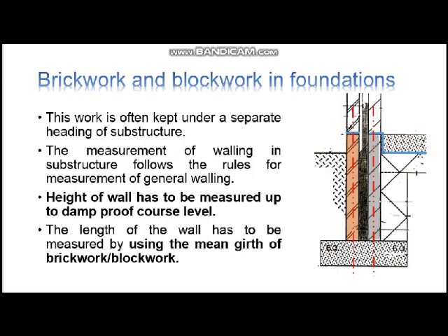Now we go to brickwork and blockwork in foundation. Normally it will be measured separately. So this red color indicates the brickwork and this blue color indicates the blockwork. We measure the brickwork and blockwork in meter square, meaning that you need to identify the height from where it sits to the DPC level. So you need to find the height of this wall for both of them.